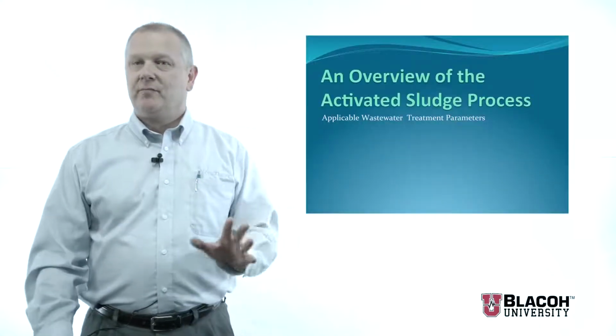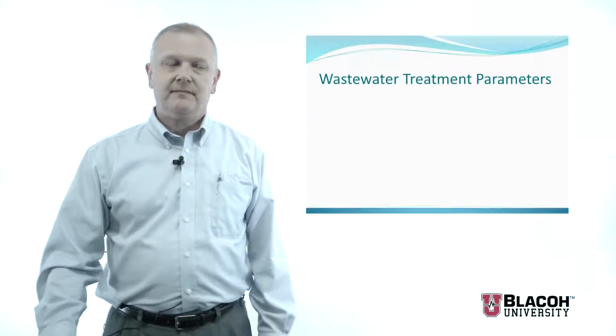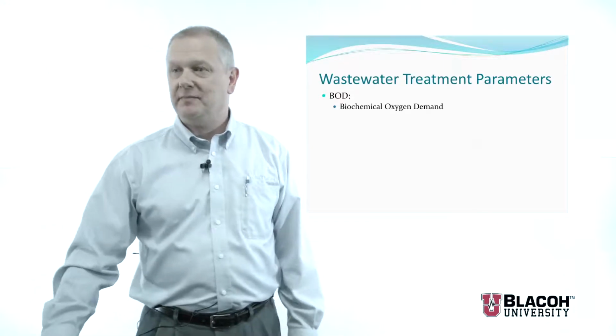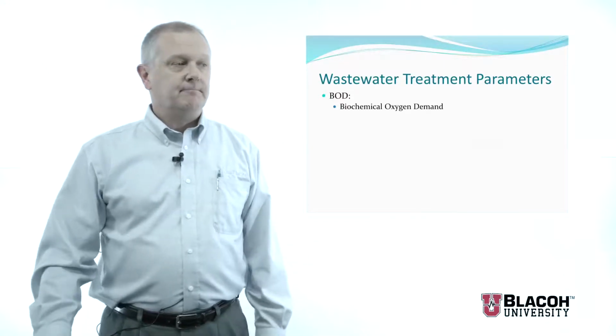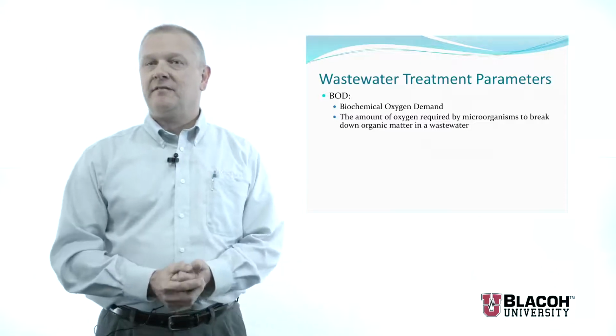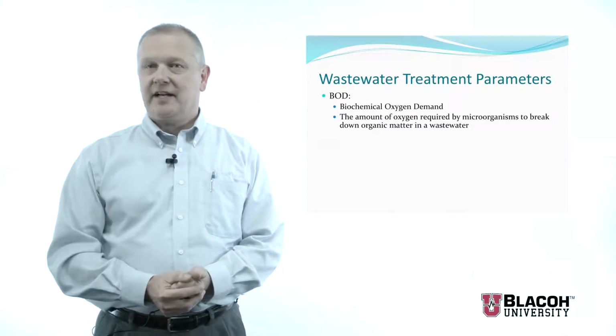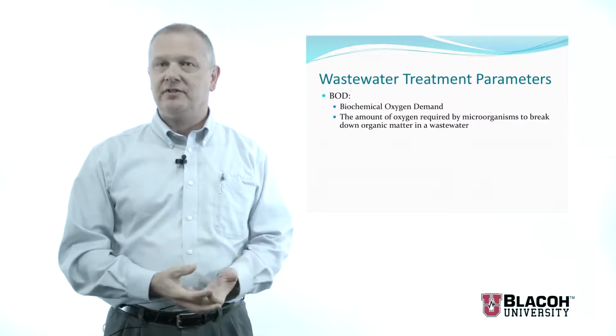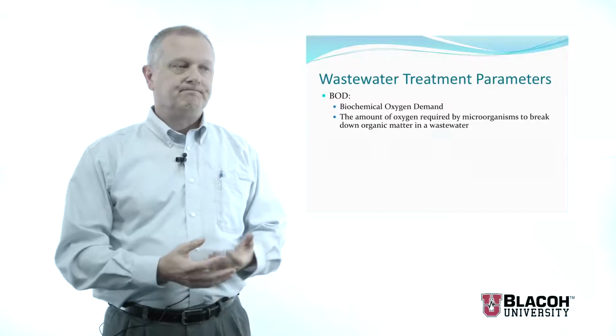A couple of important treatment parameters that we want to talk about. The first one we call BOD. That stands for biochemical oxygen demand. This is a measurement of the amount of oxygen it takes for microorganisms to break down the organic material in sewage.